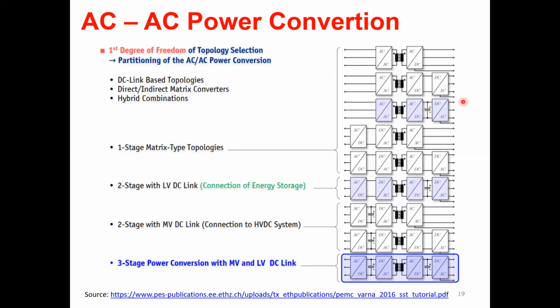So then you can have this as a three-phase inverter, just like a typical inverter. So there is nothing much changing there. There are multiple combinations like this. I don't want to go through everything. And then finally, you use a PWM rectifier and then just an isolated DC-DC and then another inverter. So basically this has a much larger electrolytic capacitor right here. So that is a configuration which at this time is, I would say, more famous,